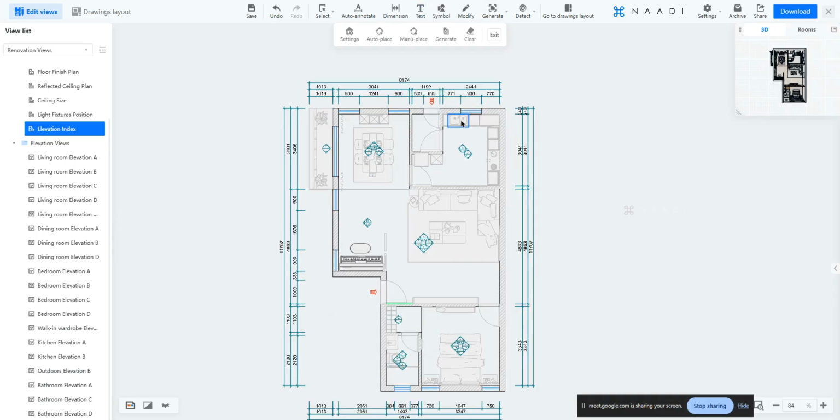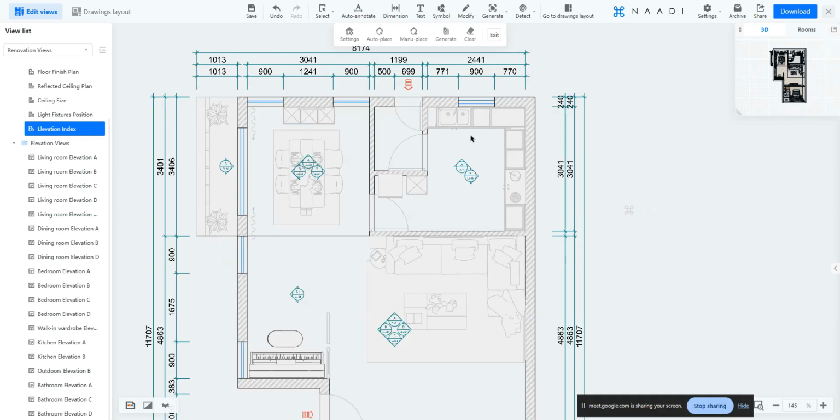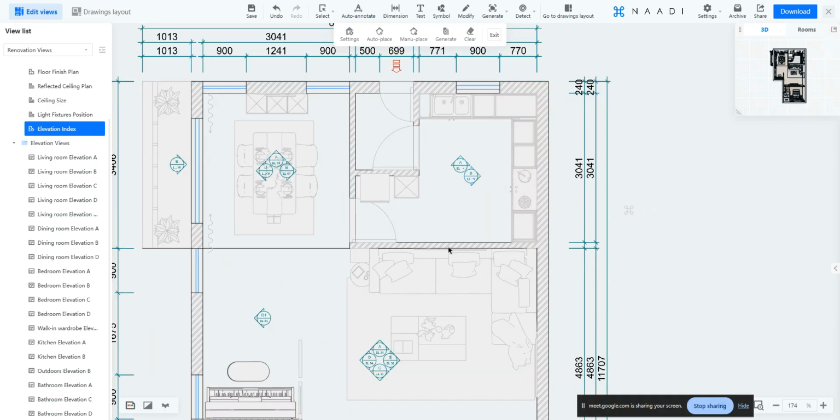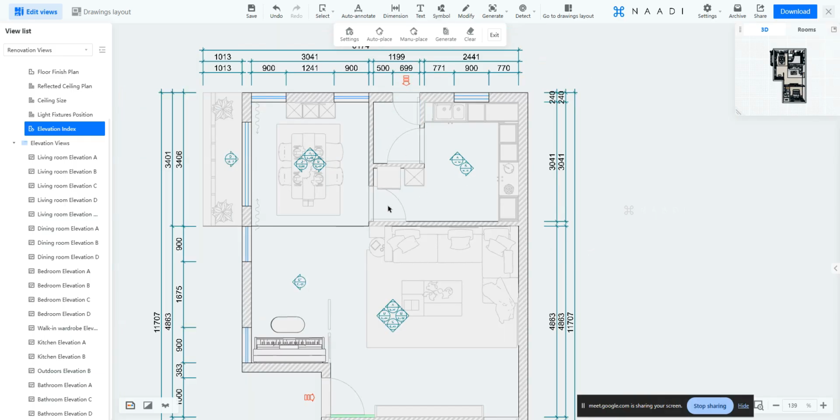In some cases you might unknowingly delete an elevation tag. For example, in this scenario itself, if you notice, I've deleted many dimensions and many elevation tags here. That was a voluntary decision so that it won't look messy. But let's say that I unknowingly deleted an elevation tag like what I did. In those cases, how can I get it back? You can just manually place one in that region.